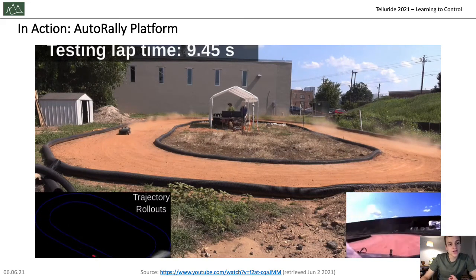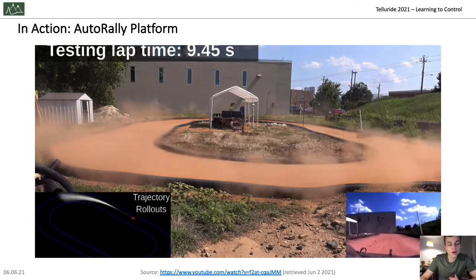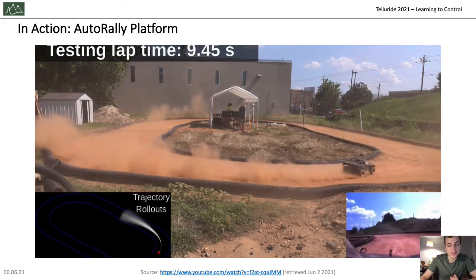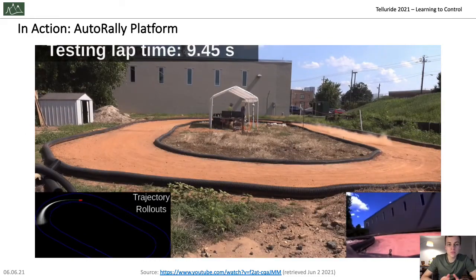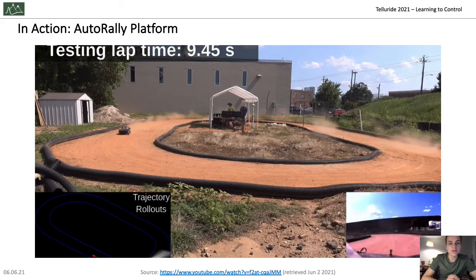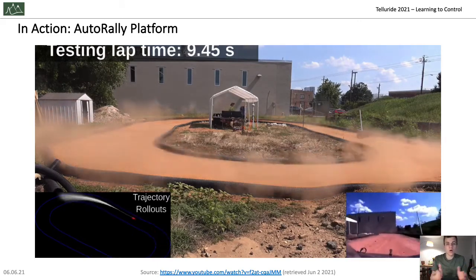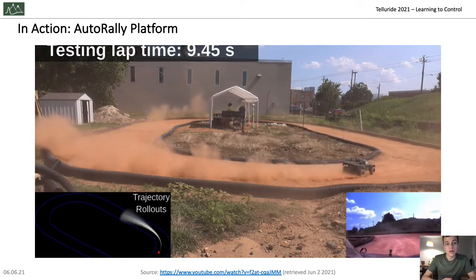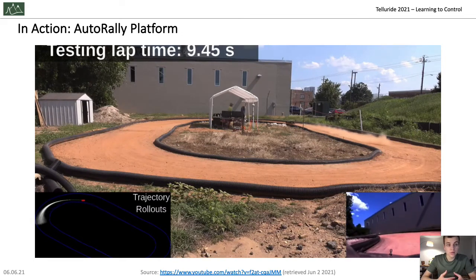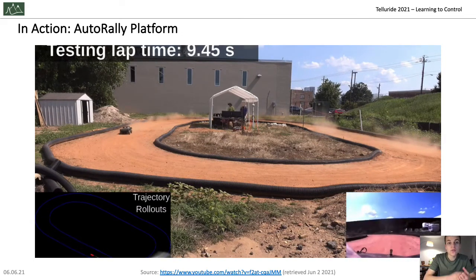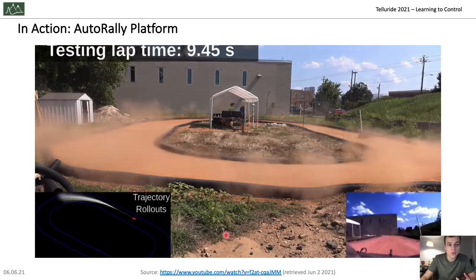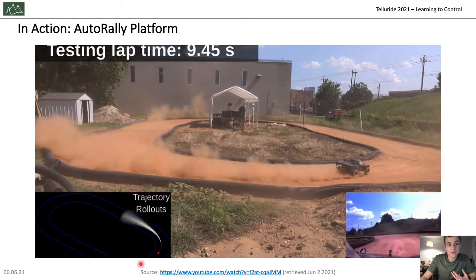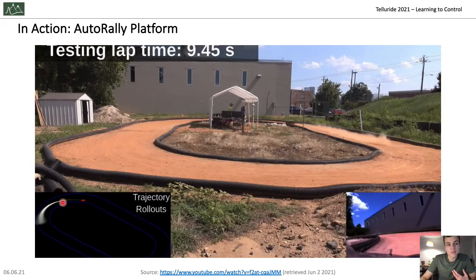So in the bottom left, you can actually see how every one of the rollouts in computation is one of those white lines. And because there are thousands of them in this real experiment, you can only see this kind of cone of exploration. And you can see that by randomly changing inputs on these future paths, you can generate a widening cone of where the car should end up. And those computations are made using a trained model of the environment. Of course, there's no access to a perfect model, but using some kind of imperfect trained model, you can really do these computations and view what the controller sees, right? So you can really see this cone of trajectories that you're exploring, and how with this weighted sum, the controller kind of decides on some line in the middle of that.